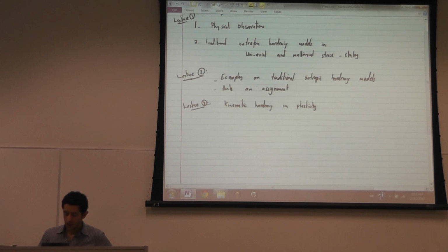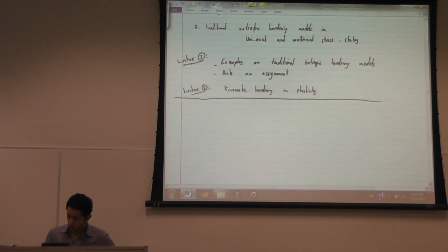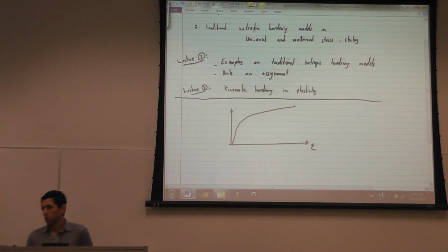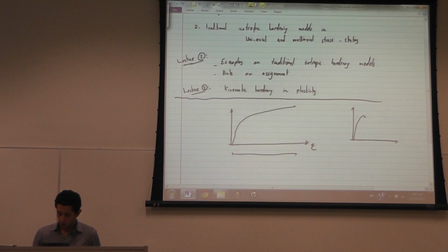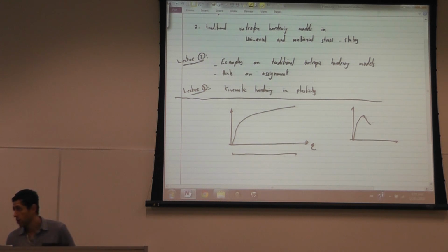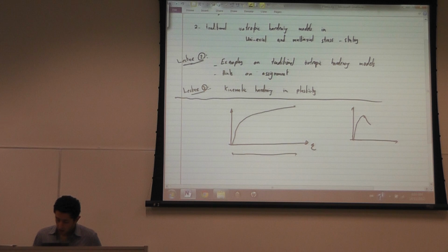Because metals are very ductile, you're able to take the strain up to large amounts, and the stress is still increasing. When you look at the plasticity of soils or concrete, these models are more complicated because you don't have this ductility in the material, and so you end up with instabilities right away, and the behavior after the peak goes down, so it's really very hard to model.